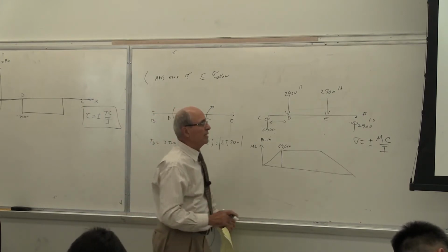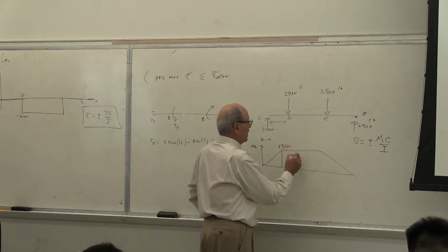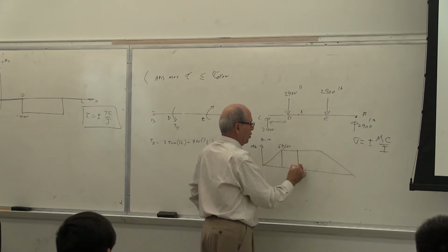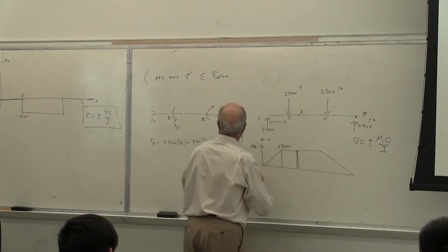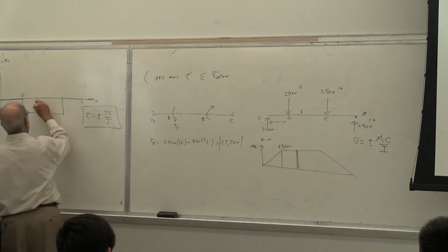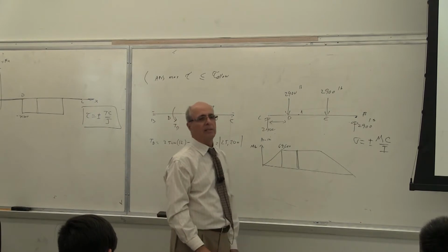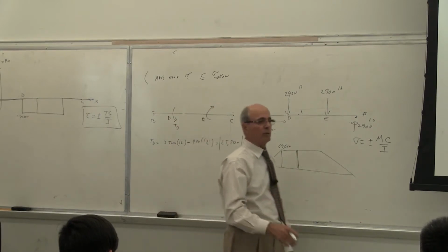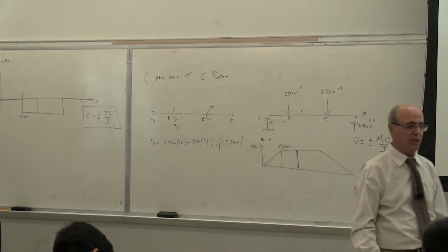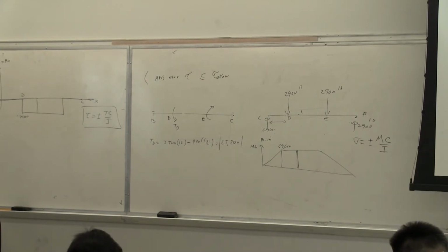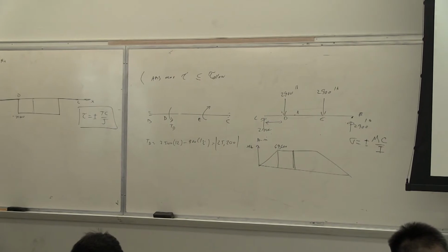The point I'm making is this. For this point A, which was here, I only have a sigma. I have a torque, yes or no? And I have no transverse shear. Is that correct? However, write a note for yourself. Even if you have transverse shear in your problem, we are going to neglect it or assume it is negligible. There is a reason for it.